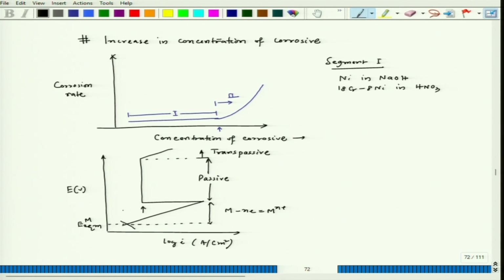This particular current density corresponds to Ip, which is the lowest current in that particular anodic part. Of course, if I try to see the interaction with the cathodic reaction, then this can sometimes be the lowest current density. For example, if the cathodic part interacts here, then this is the cathodic part which corresponds to IC. So, then this becomes I corr.